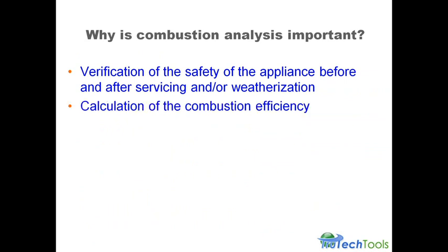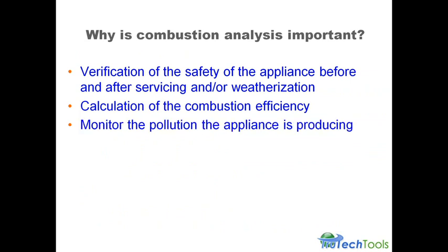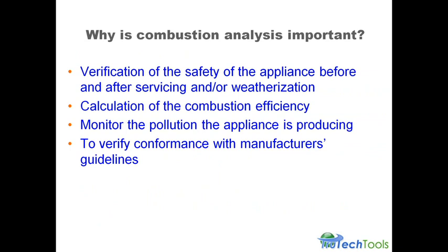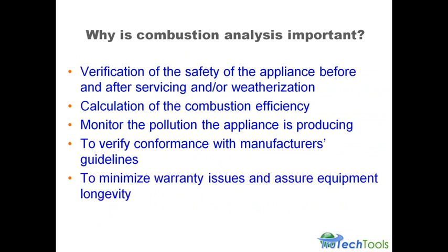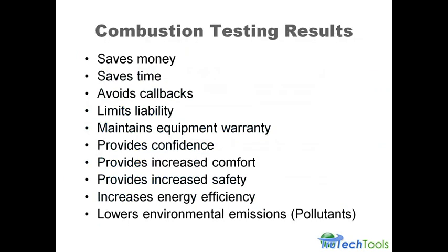We want to calculate the combustion efficiency and see how the appliance is operating. We want to monitor the appliance for pollution. So we want to see, is it producing NOx or is it producing CO? We want to verify conformance with the manufacturer's guidelines, and we want to try and minimize any warranty issues and assure the equipment longevity.